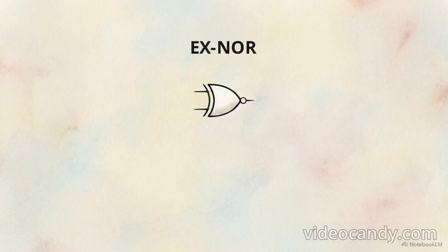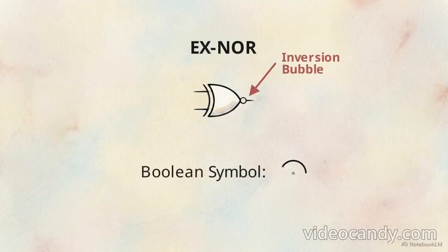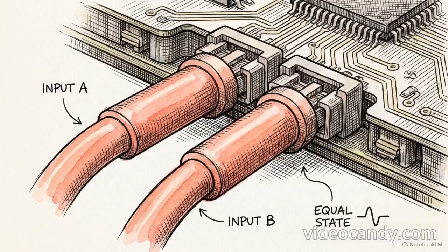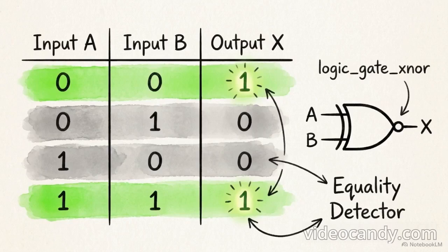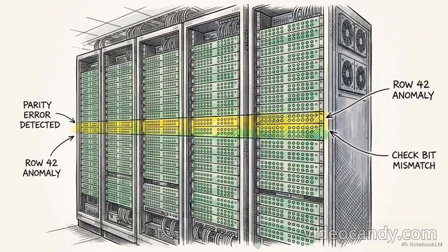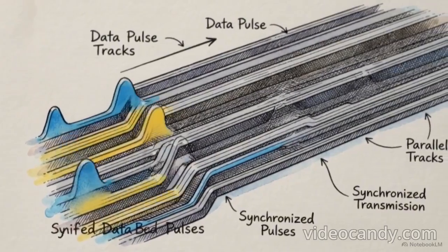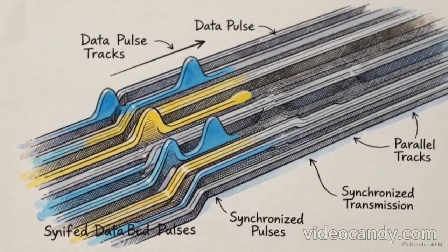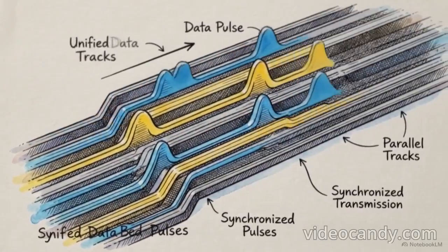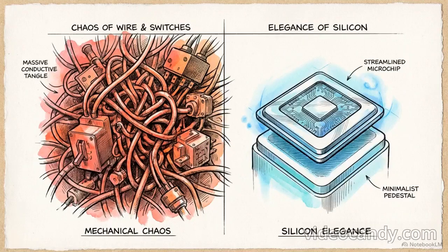This is the direct complement to the XOR function, marked on schematics by an inversion bubble and a circled dot symbol. Its operational rule is the exact opposite. The output goes to logic high only when all inputs match, operating as a dedicated equality detector. Engineers deploy XNOR gates heavily in parity checking and system error detection circuits. It continuously compares bits of data transmitted across a computer bus, verifying that the arriving voltage levels perfectly match the data originally sent. Exclusive gates prevent engineers from having to manually build massive, slow, basic gate arrays just to compare two pieces of data.